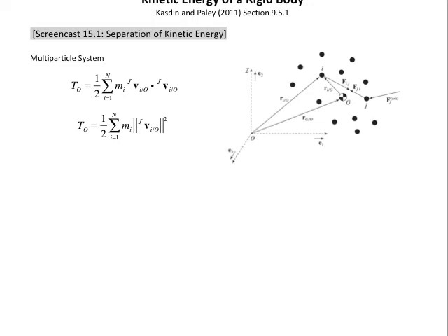In this screencast, we establish the expressions that we need to find the total kinetic energy for a rigid body. And we do that by starting with a multi-particle system and establishing the separation principle of kinetic energy.